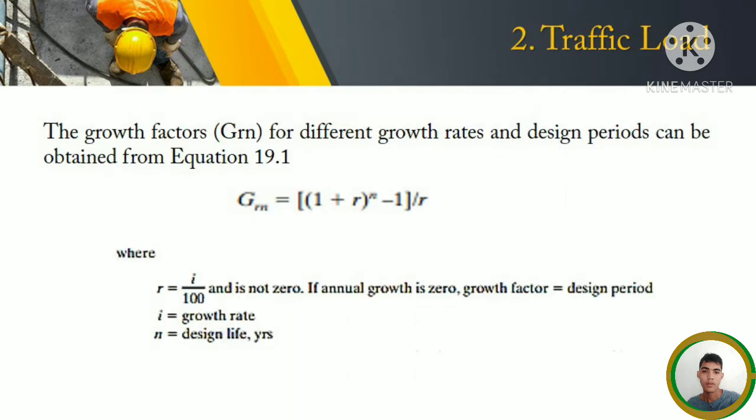So, the total ESAL applied on the highway during its design period can be determined only after the design period and the traffic growth factors are known. The design period is the number of years the pavement will effectively continue to carry the traffic load without requiring an overlay. Flexible highway pavements are usually designed for a 20-year period.